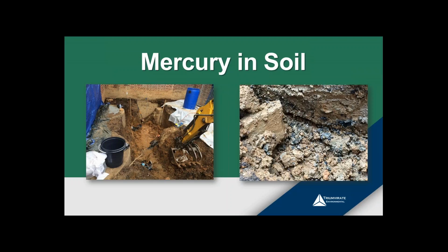In Massachusetts, the Method 3 upper concentration limit, UCL, for groundwater and soil is 200 micrograms per liter and 300 micrograms per gram. Now these concentrations vary per state, and in most states they actually vary with depth. So in regards to human health and potential exposure, usually the top layer of soil has the higher concentration limit, and limits increase as depth increases. This is realizing that mercury is naturally found in soil, so it's just taking that into consideration.